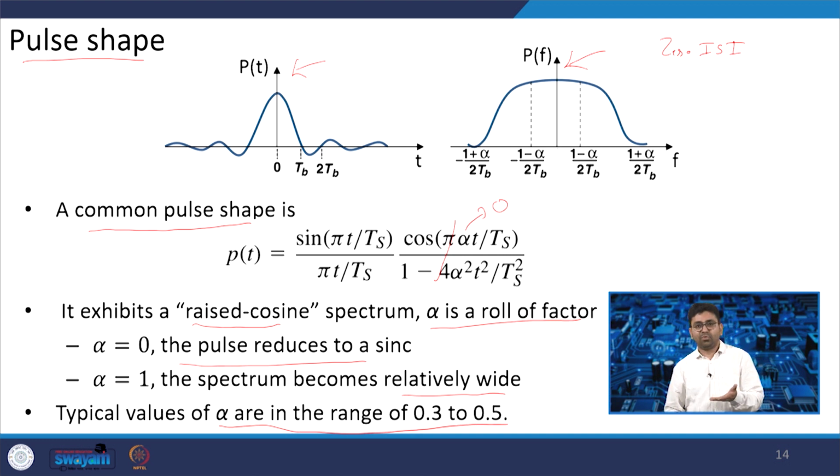If we use more than 0.5, then your signal will have a wider bandwidth and will observe ISI. So, we need to use pulse shaping in order to reduce the ISI, and it is widely used in digital communication. This raised cosine function can be applied to your bit stream, and you can make a pulse shaped bit stream.